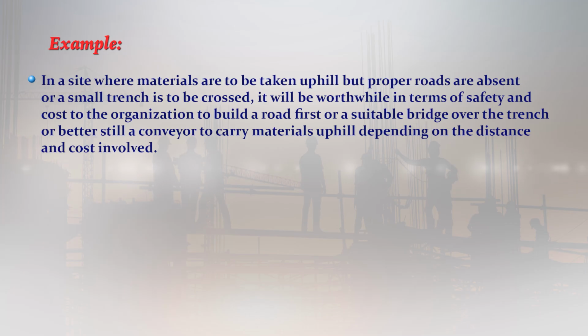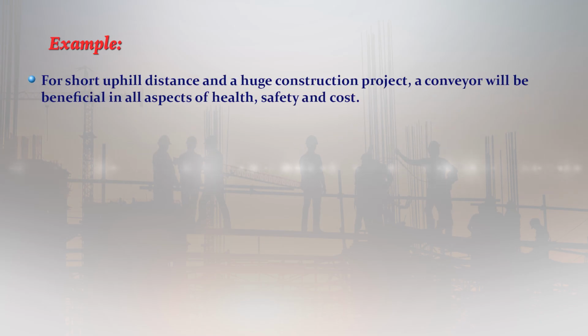For example, in a site where materials are to be taken uphill, but proper roads are absent, or a small trench is to be crossed, it will be worthwhile in terms of safety and cost to the organization to build a road first, or a suitable bridge over the trench, or better still a conveyor to carry the material uphill, depending on the distance and the cost involved. For short uphill distance, and a huge construction project, a conveyor will be beneficial in all aspects of health, safety and cost.